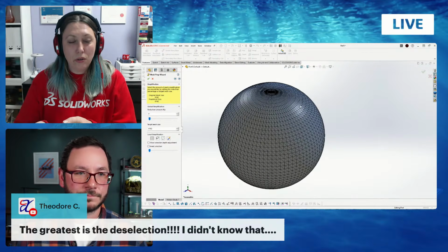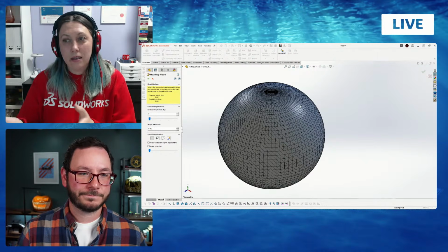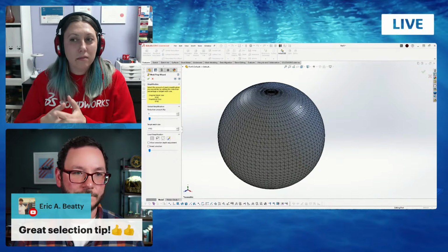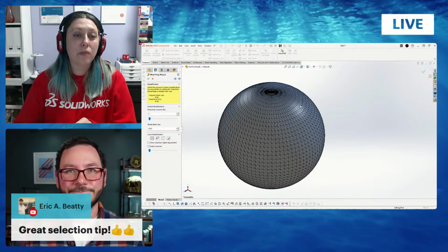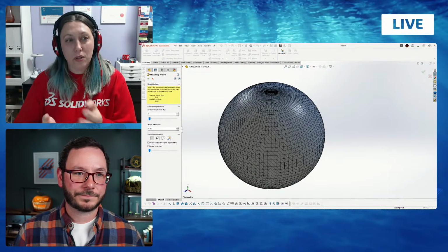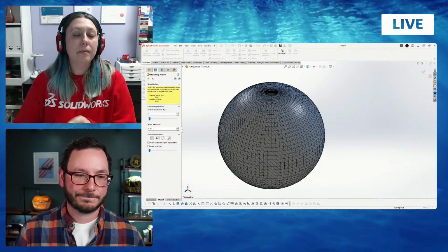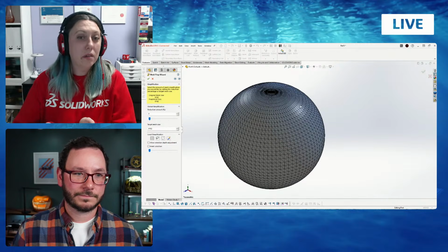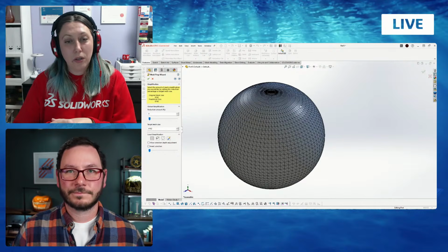When you don't need the SOLIDWORKS data, or you have a very complex file, like I said, like the dragon, it's not that it's impossible, but it's close to impossible to convert it to SOLIDWORKS entities. In this case, it's better to use the standard mesh import and just convert to mesh body. But when you have some geometric data and things that can be converted, then it's better to use Scan to 3D because it has a better tool set.